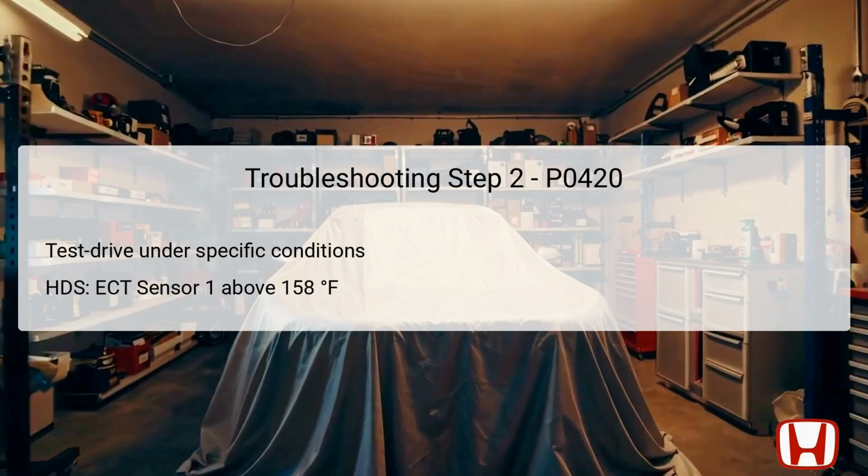In this step of troubleshooting, you need to test drive the vehicle under specific conditions to evaluate the performance of the catalytic converter further. The temperature of the engine coolant, monitored through the engine coolant temperature ECT sensor 1, should be above 158 degrees Fahrenheit, 70 degrees Celsius to ensure that the vehicle is functioning correctly.